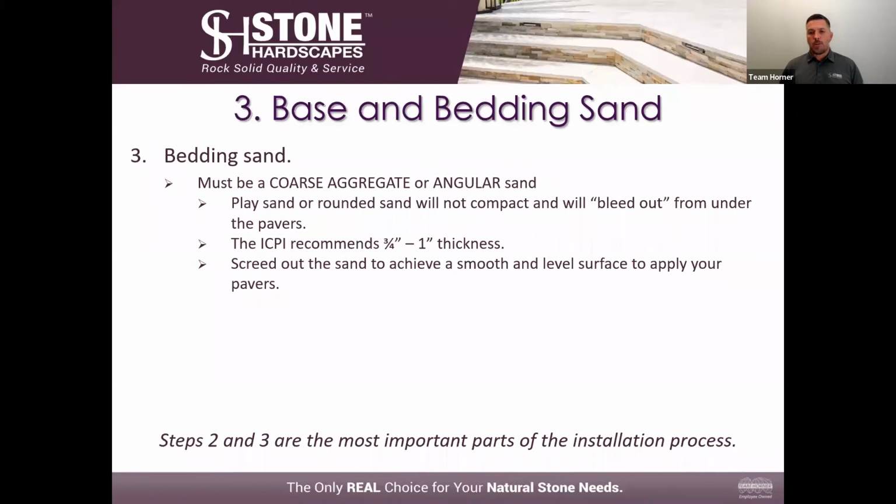Now, the ICPI will recommend between 3/4 and an inch of thickness. Once you put the sand in, you're going to rake it out, and then you're going to screed it out like you're troweling concrete, and that's going to give you a really nice surface.